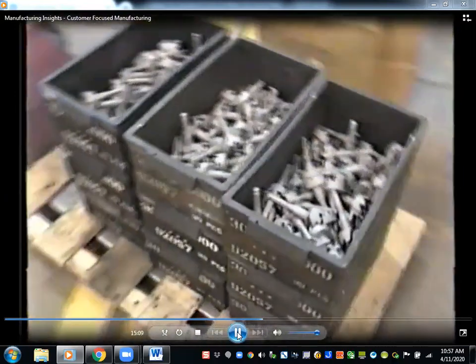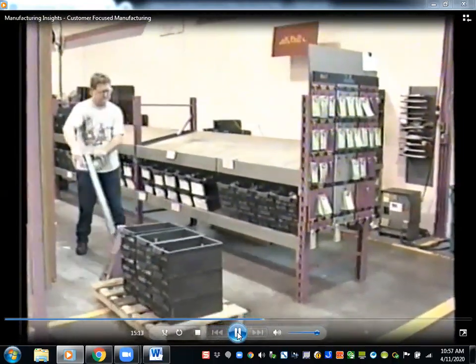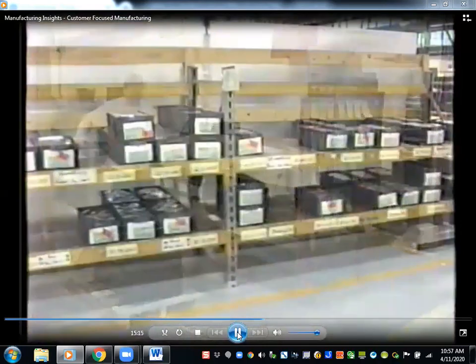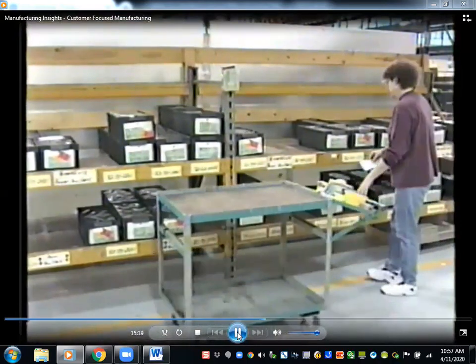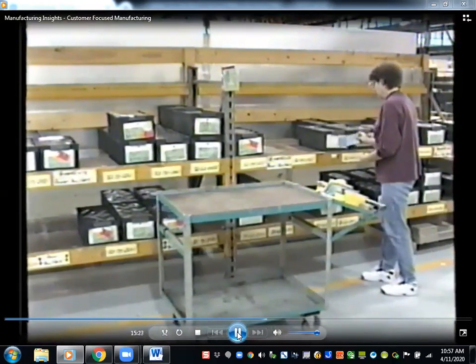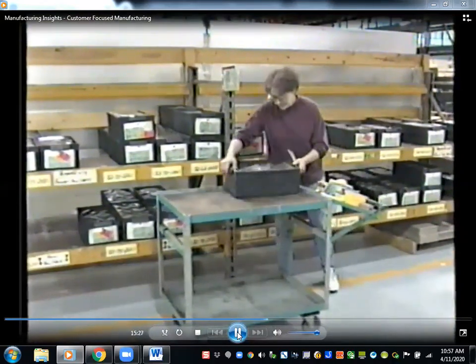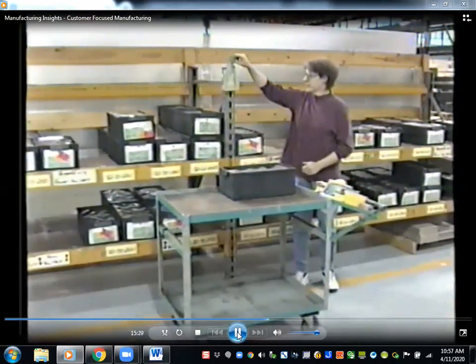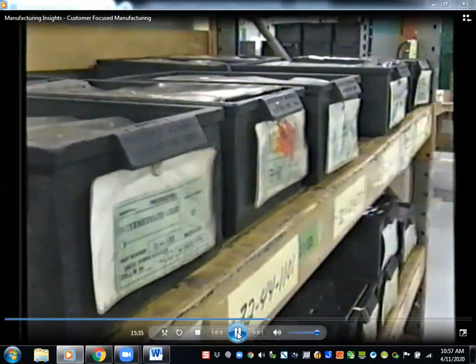An important element in the operation of each cell is the use of a Kanban pull-type inventory management system. Unlike traditional push systems, where inventory is manufactured according to a schedule planned far in advance, the Kanban system produces items only as they are needed, or to replace items already used in production. With Kanban, material is not issued until a signal comes from the user of the item.